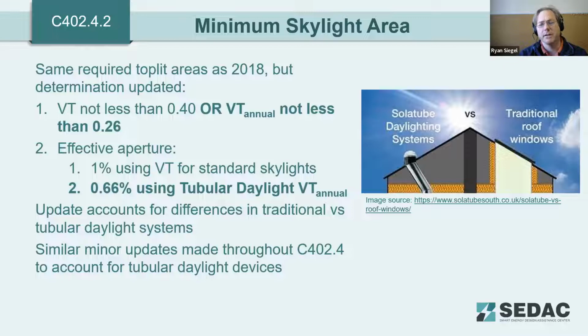Understanding that the sun may move, and with now more dynamic glazing areas and seeing more dynamic skylights, during the middle of the day when the sun is brightest, that dynamic glazing is going to reduce its visible transmittance and perhaps improve its performance during those brightest hours.